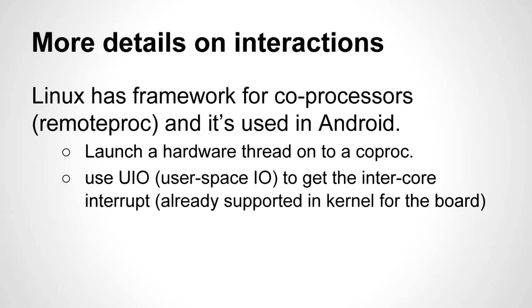What he has working right now is basically mapping /dev/mem and starting peeking and poking. And obviously he's looking at things like remoteproc and worrying about that. And the key thing here is he's also using UIO to get the interrupts.